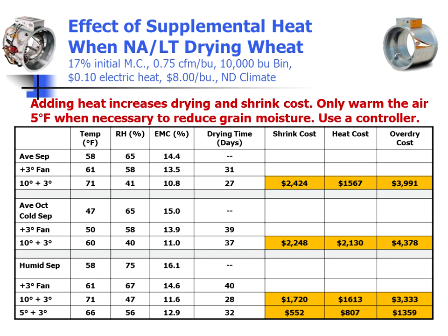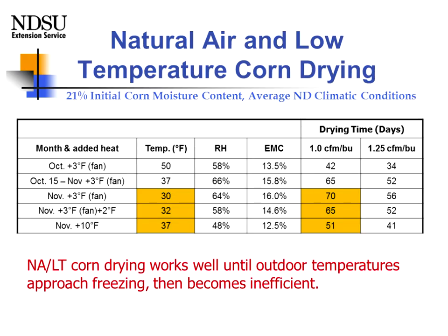If we add 10 degrees, again, we're over-drying. Just a 5-degree temperature rise will bring us to roughly 13% moisture and minimizes those over-drying charges. So there's probably places where this rule of thumb will not apply, but in general I say that about a 5-degree temperature rise is all that we will need, and we'll even look at that as we look at corn.